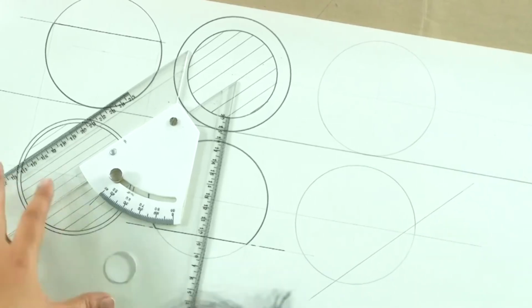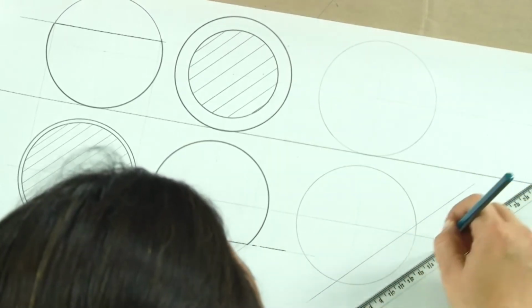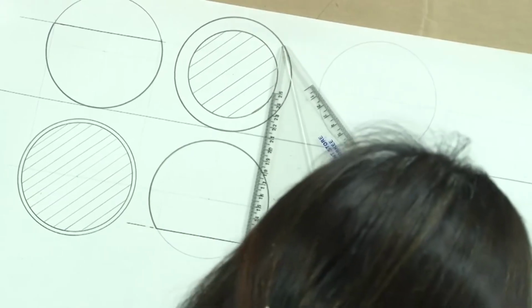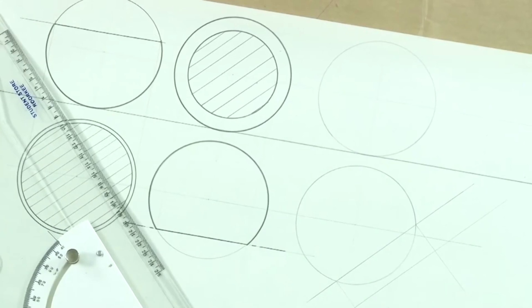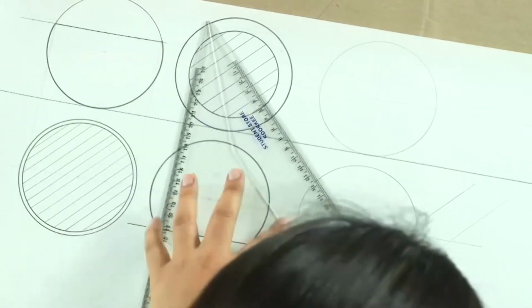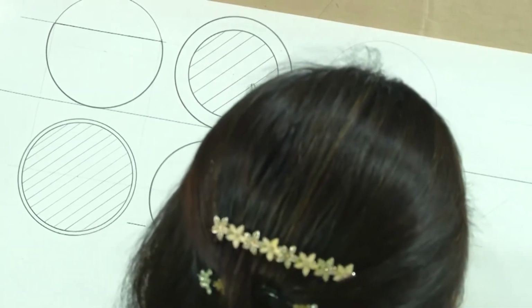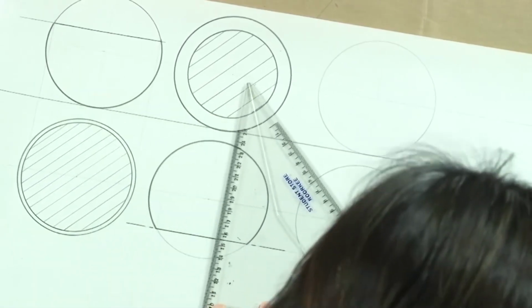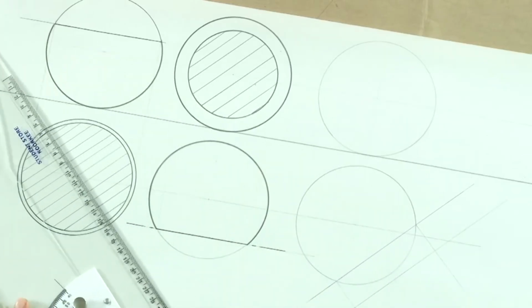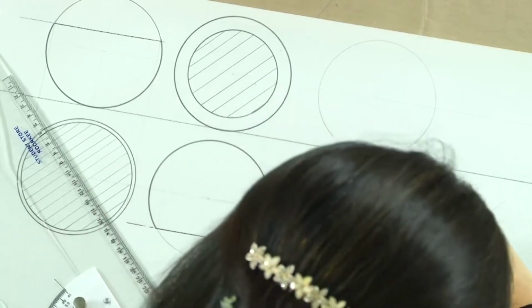Now, how do we see it? So, what we actually have is, we will be seeing the true shape of this section here in the auxiliary plane, which is going to be parallel to the section plane, and the line passing through the center of the sphere is going to be the line where the center of the circle lies, because we know for sure that this true shape of the section is going to be a circle, that is confirmed.